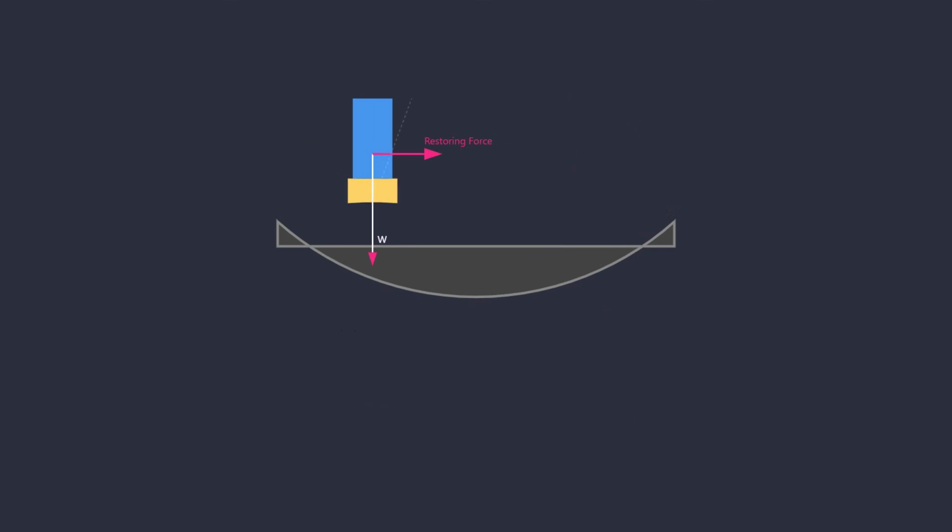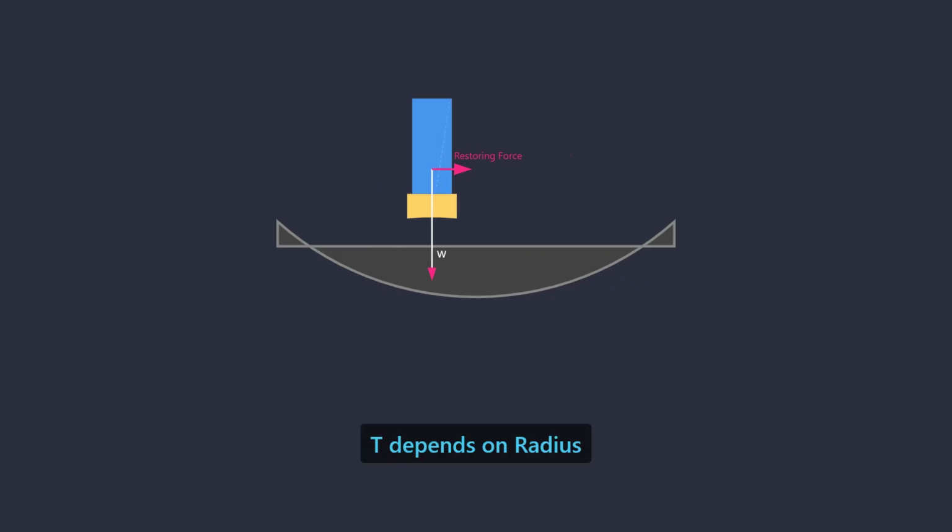Friction pendulum systems, or FPS, utilize an articulated slider resting on a concave spherical surface. This mechanism physically isolates the structure. During intense ground motion, the slider moves along the curved plate, causing the structure to lift slightly against gravity. This lifting action generates a natural restoring force, acting precisely like a pendulum. The restoring force is proportional to the structure's weight and inversely proportional to the radius of curvature of the plate.